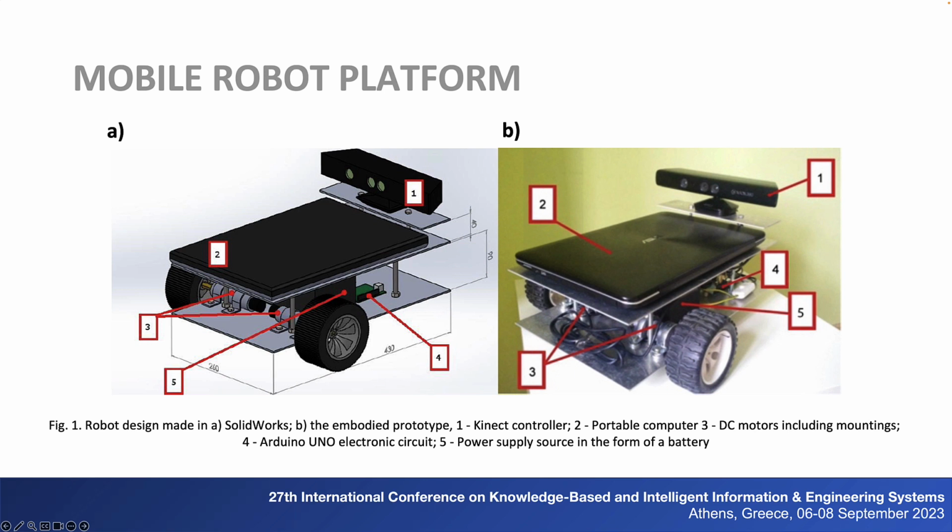The camera's field of view is 43 degrees vertically and 57 degrees horizontally. The depth sensor range is 0.5 to 6 meters. The refresh rate of the image is 30 Hz. The device is powered with 12V, at a current consumption of approximately 1.08 A.